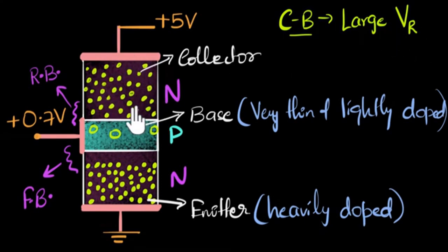I like to remember our Zener diode. Remember, a Zener diode is very heavily doped, and under such heavy doping, it has a small breakdown voltage. That's a specialty. Well, lighter doping means larger breakdown voltage. So if you need more clarity on how that happens and how the depletion region gets affected, it would be a great idea to go back and watch that video on Zener diode again. But anyways, to make sure that this reverse breakdown voltage is high enough, the collector is usually lightly doped. You get that? It's nothing to do with our operation of amplification, but just to make sure it doesn't undergo breakdown. So this is lightly doped.